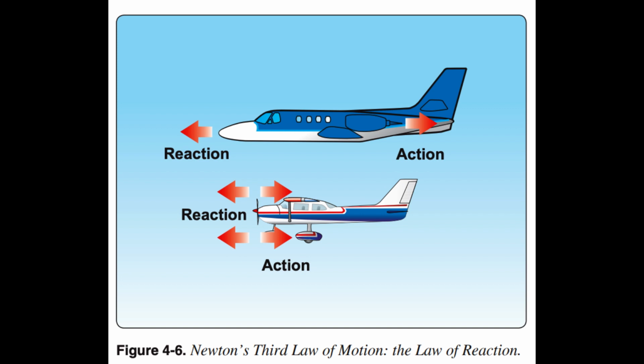The tropopause is the thin layer between the troposphere and the stratosphere. It varies in both thickness and altitude, but is generally defined where the standard lapse, generally accepted at 2 degrees Celsius per 1,000 feet, decreases significantly, usually down to 1 degree Celsius or less.